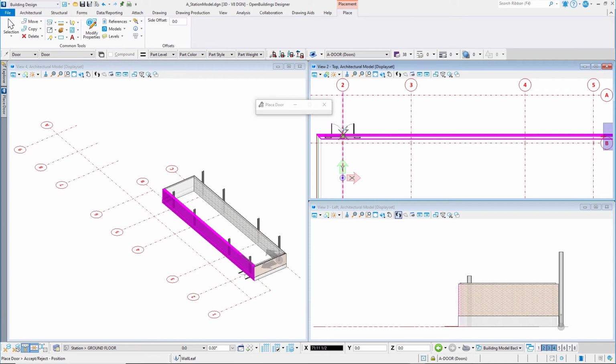Snap to grid line 2, then type O on the keyboard to move the AccuDraw compass to the current snap location. Now move the cursor towards column line 3 and use Enter to lock the axis. Snap to column line 3. Type / and then 2 on the keyboard to divide this distance between the 2 points in half. The cursor moves to the midpoint between the 2 grid lines. Now, data point left-click to accept the placement point.